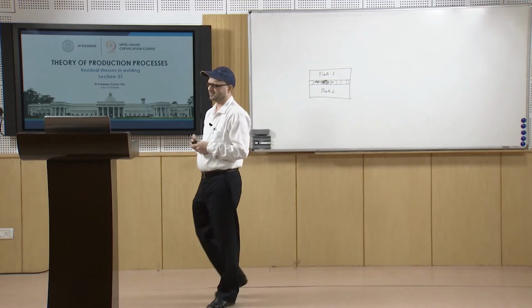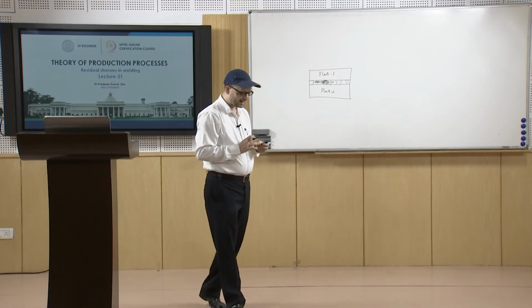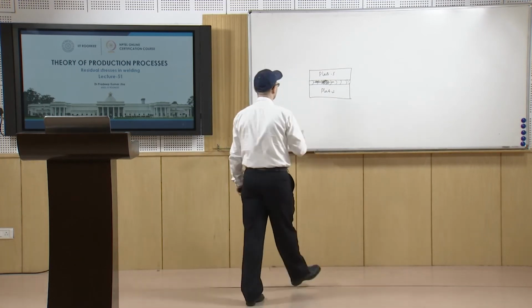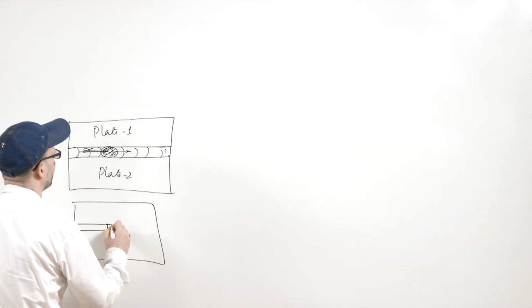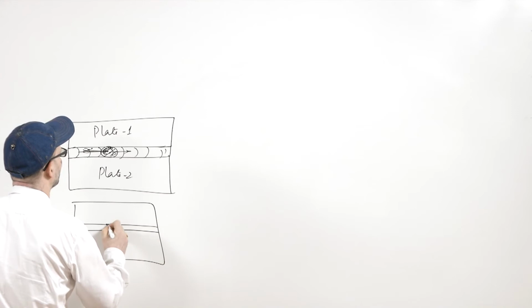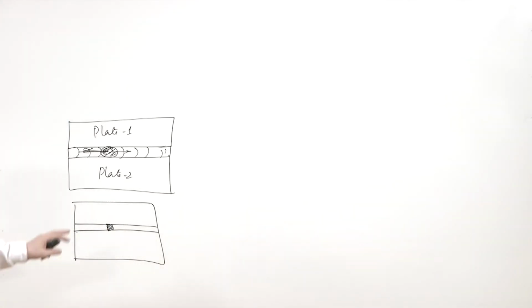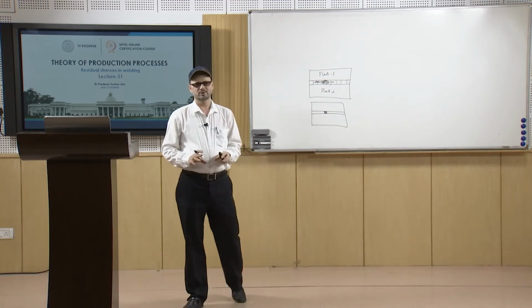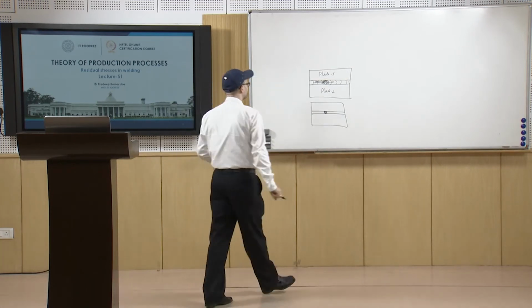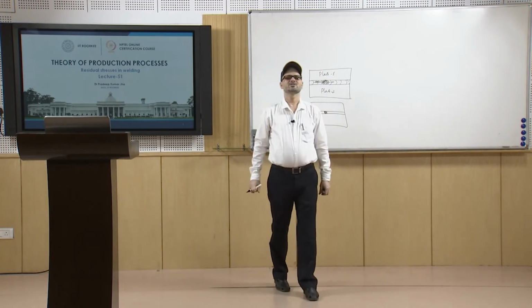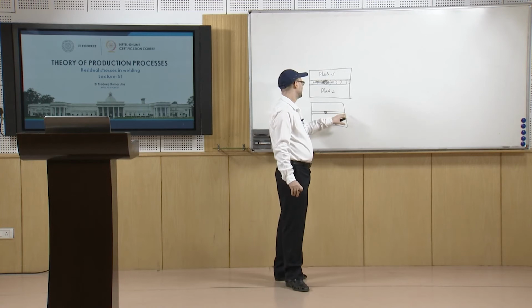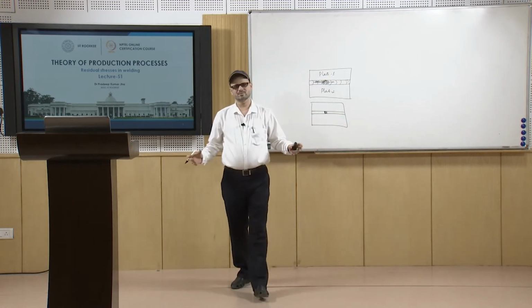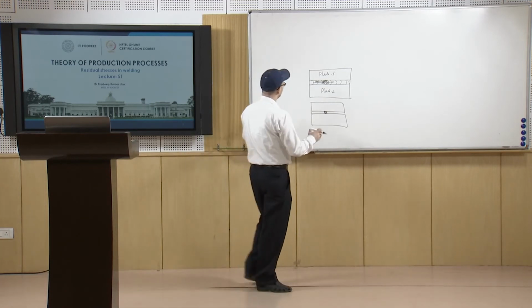Then comes another type of stress which is developed, the reaction stresses. Many a times when we are welding, suppose we have some type of structure where we have the two ends, and we are doing the welding here. Once you are doing the welding, stresses are developed, and it will try to expand or contract depending upon the temperature or cooling conditions. Since it has restraint from the sides, it cannot freely move, because it is either fixed at these ends, or in whatever way they may be having a certain kind of joint.